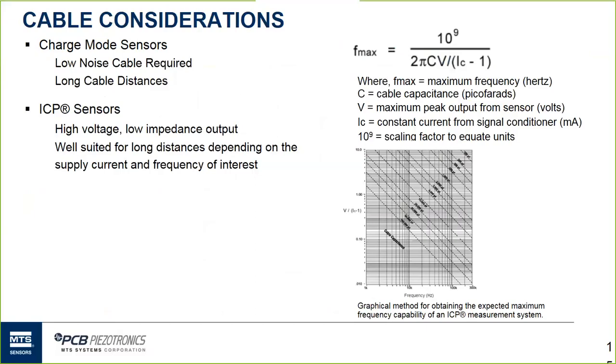as well as its capacitance. That's really a discussion in itself at times, but something I wanted to at least touch on to give you an overall view of making sure that you take the cable into consideration with regard to its durability, suitability for the application, and the environment that the sensor is going to be used in.